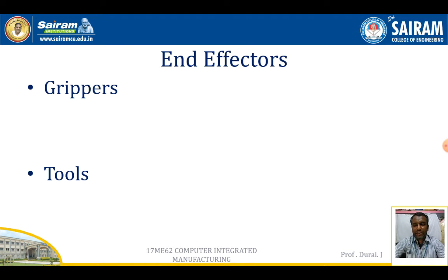Hydraulic drives are used to run the large and more powerful robots. These were the primary source of power in the earlier days, and these drives have greater strength because they produce the highest power in a given small volume. The advantages of this one are high power, high power-to-weight ratio, and high strength. Disadvantages are that they are very noisy and require large space.